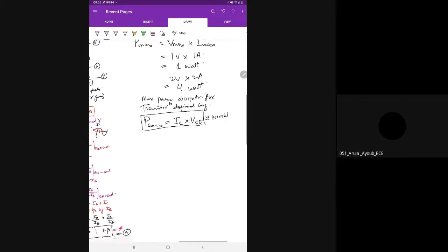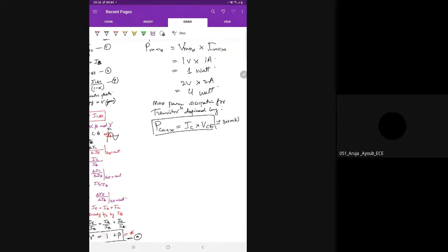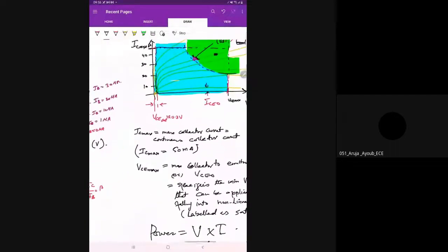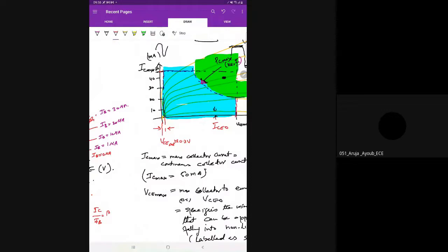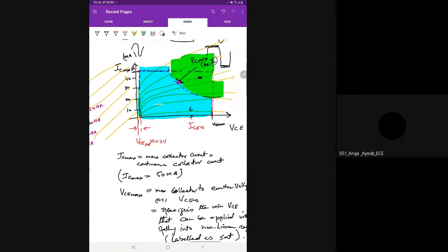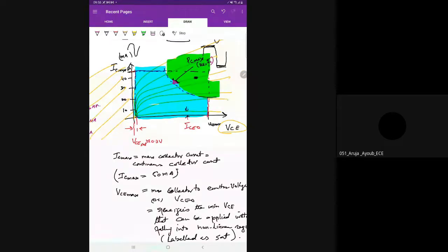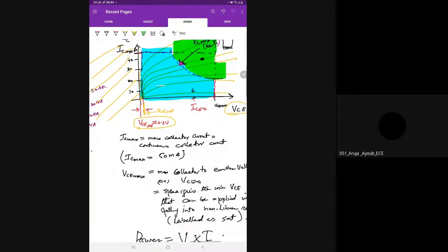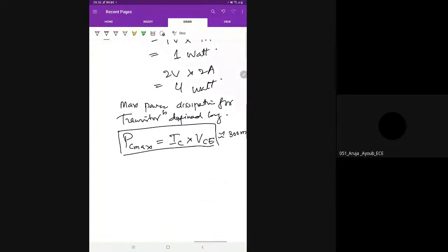Okay. Now see, the saturation region is defined in this graph. What is the saturation region? Saturation region ये वाला है, somewhere here. Okay, it is this region. This is the saturation region. So saturation region is when VCE, this is VCE, when VCE is less than VCE saturation. So this is the VCE saturation point. जब VCE उससे कम होगा तभी आपका saturation region मार्क हो रहा है इस ग्राफ से. So we can write down here the saturation region.